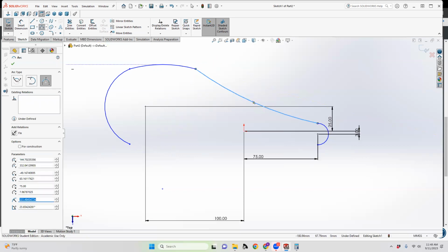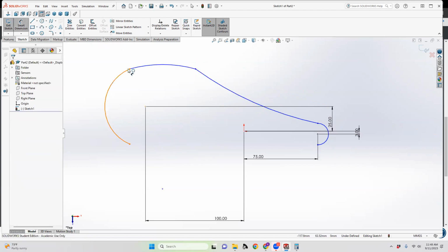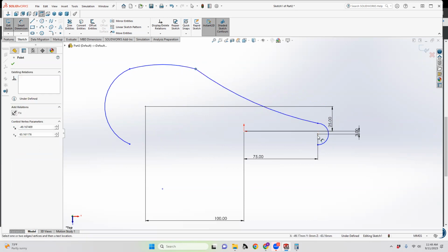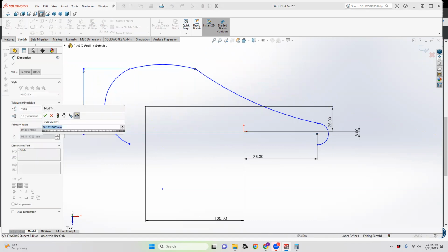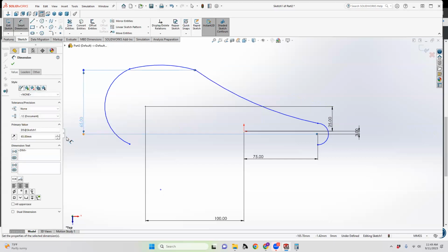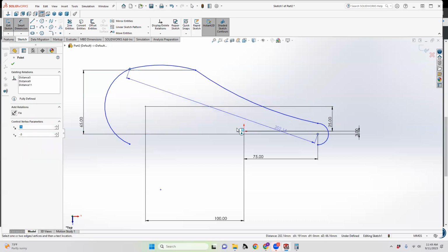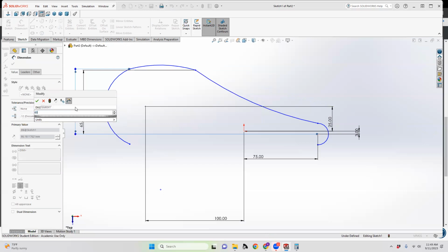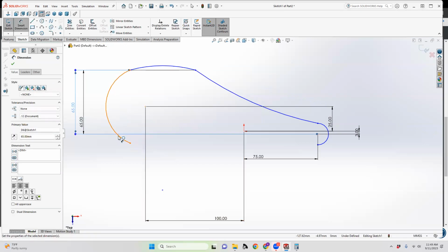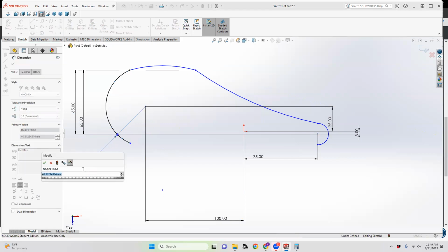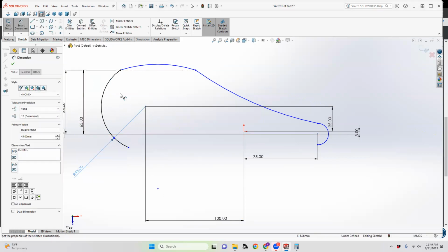And then what this will do is this will allow me to set a couple of the things that are needed, like, for instance, what's the height of this point relative to this axis, which is going to be the Z. So you're drawing in the XZ plane for this one. So maybe that only needs to be 65. And maybe this needs to be 65 also. So those are parallel. And maybe this radius actually needs to be 45. So now this one's fully defined.